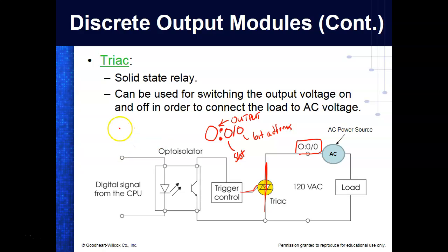So what do you think I would put for N? I'd put I, then I'd put colon, and then I'd specify a slot number, like slot number 1, then I'd put a slash and specify a bit. So that would be in slot 1, bit 6. So that would be on the 1100, that would be the first module on the right.